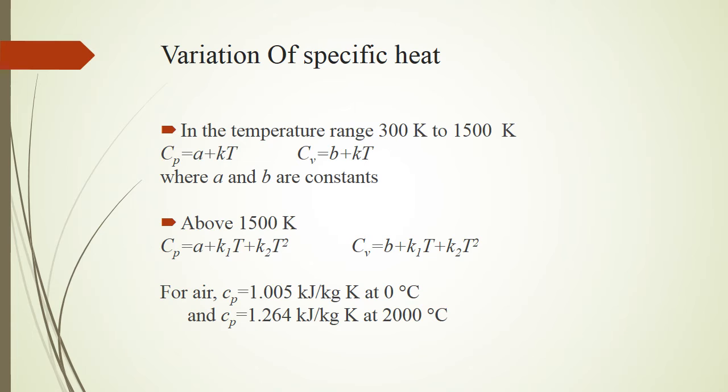Why does specific heat increase with an increase in temperature? As the temperature increases, a larger fraction of heat would be required to produce the motion of atoms within the molecules. As the temperature is the consequence of the motion of molecules as a whole, the energy which goes into moving the atoms does not contribute to a proportional temperature rise. Hence, more heat is required to raise the temperature of unit mass through 1 degree at higher levels. This is basically the definition of a specific heat.